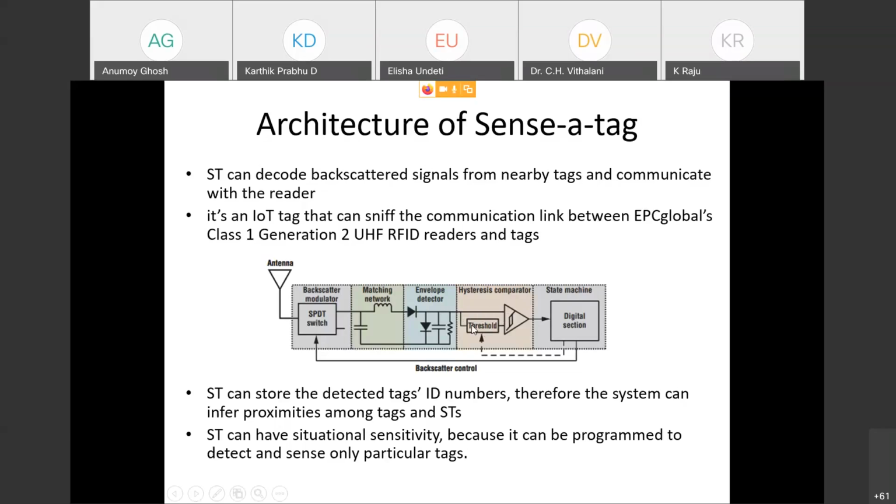So the threshold is 10 meters. Comparing it with 8 meters, say it is giving 2 volt. So 2 volt is mapped to just alert in the digital section. Say 2 volt is mapped to 0 1. 0 1 is only triggering alert. So whenever it is 0 1, according to it, SPDT will work, and then it will just alert the driver.